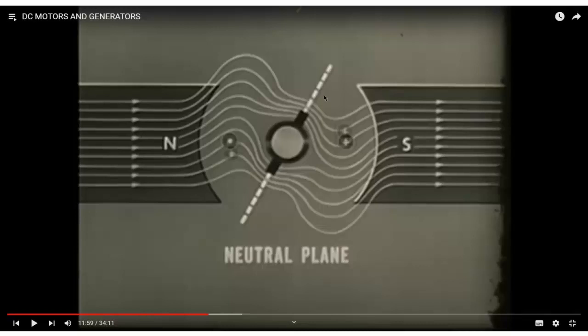In a generator, we move brushes in rotation direction a little bit to keep sparks as low as possible. You adjust, and when you see the smallest spark position, you leave the adjustment. You just check by your eyes.